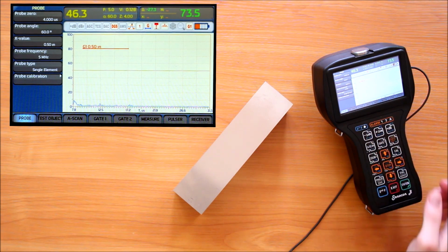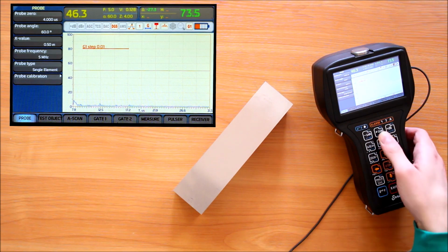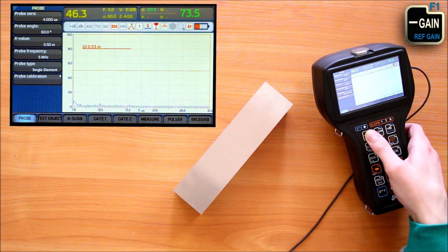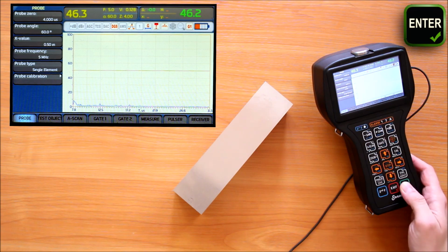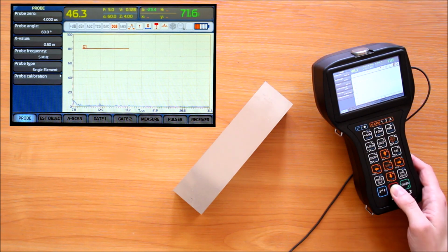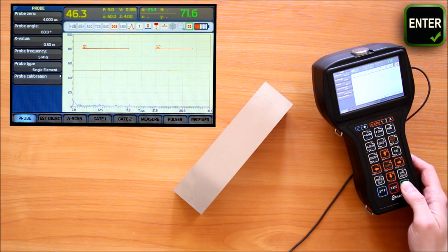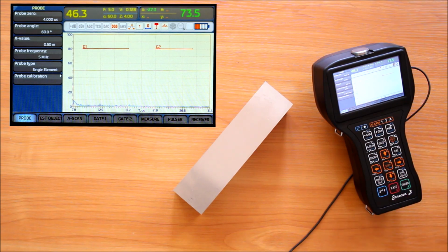When changing one of the gate parameters, the step button would cycle its increment-decrement step. Enter button would switch the gate on and off. To exit the first gate direct control mode, we can press Exit button. Second function plus Gate 1 buttons would do the same with the second gate for us. For more gate settings, we will have to use gate 1 or gate 2 menu.